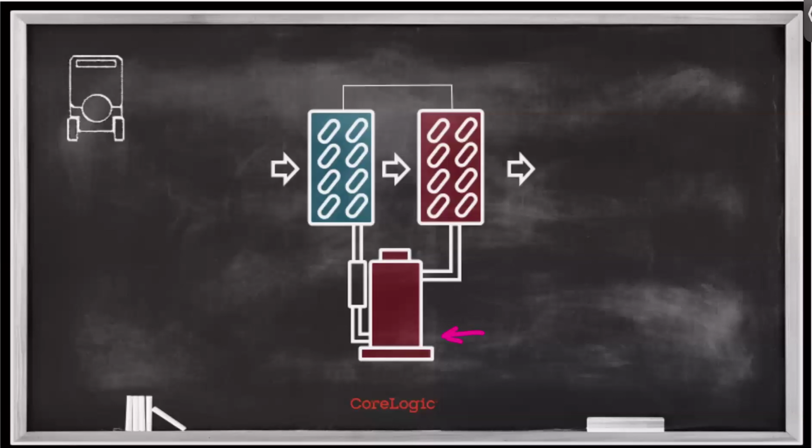Now, the refrigerant inside of this system is being pressed into one coil that looks a lot like the radiator in a car, right? It's a bunch of fin tube coil design. It's then being transferred over to a second coil through a restriction device, right? That's restricting that flow into a second coil that looks a lot like the first one. And then it returns back to this little heat pump. And this refrigerant just keeps cycling through this over and over and over again.